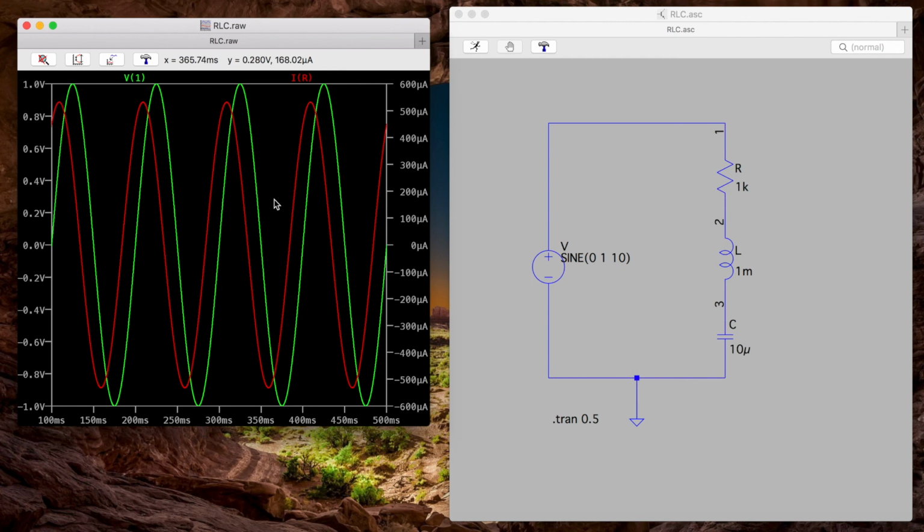Before finishing, I just want to add something concerning your exercise. Sometimes we may give you only the amplitude of the voltage applied on the circuit, but not the phase. So in this case, you have the choice of the phase, and the result then will follow this choice. And I just want to show you this idea.